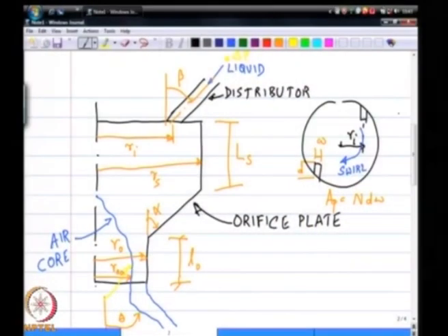Now, if I take a streamline coming to this air core all the way extended into the tank, if I can draw a streamline going from this point here all the way into the tank, which is at some high elevated pressure delta P, we are applying this Bernoulli's equation on that streamline. I can also apply it from that same tank to another point, let us say here or here, does not matter, but if all the